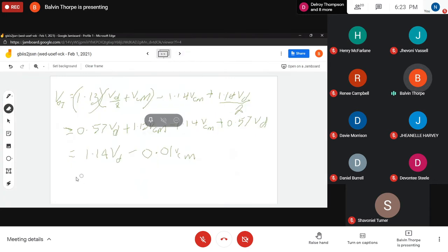All right, so this is where we are, and this is what we get. I'm moving quickly along. What you should realize by now, ladies and gentlemen, is to go back to the general expression for every operational amplifier for the output voltage. The general expression is: AD times VD plus ACM times VCM.